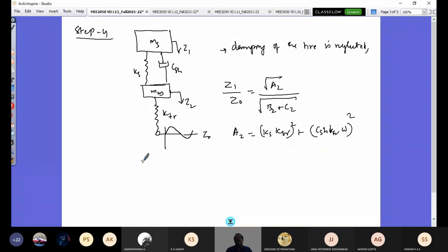And we have just now done in step 3 what its natural frequencies are. Having that, I would be able to get my transmissibility and so on. Here step 4 is to get the amplitude ratio of my sprung mass and unsprung mass for the given road input. For that purpose, this is the equation, and let's call it equation number 17. I'm going with the textbook number so that it is easy for you to follow.